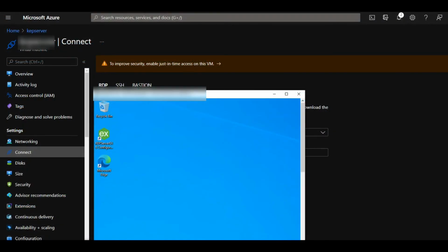Okay, the plan is to connect some industrial equipment exposing an OPC UA interface and have telemetry from that equipment flow into Azure through Azure IoT Hub. To simplify the process, I have used default security options, but I highly recommend using the security options in a production scenario. The OPC Foundation has put together some great articles on OPC UA security best practices. For this demonstration, I choose to use the free demo of KepserverEX and install it on an Azure virtual machine.